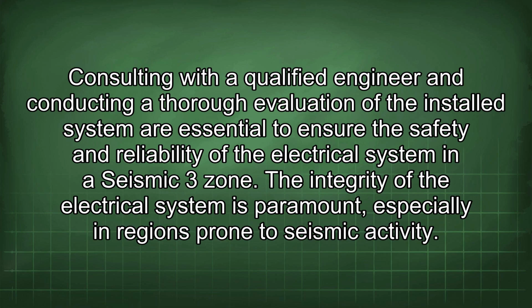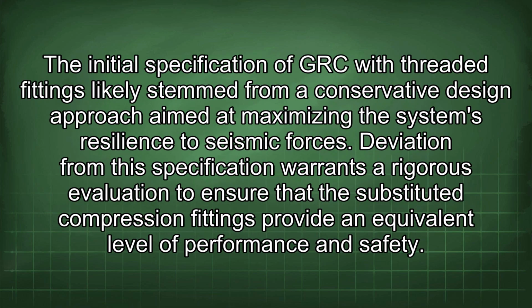The integrity of the electrical system is paramount, especially in regions prone to seismic activity. The initial specification of GRC with threaded fittings likely stemmed from a conservative design approach aimed at maximizing the system's resilience to seismic forces. Deviation from this specification warrants a rigorous evaluation to ensure that the substituted compression fittings provide an equivalent level of performance and safety.